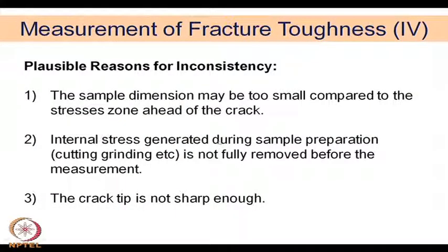ground, and annealing of these internal stresses is always difficult, because, unlike in metals and alloys, just by heating one can remove the internal stress, because it is basically a dislocation movement. Here the internal stress removal is always difficult. So, one has to take special precautions, so that during cutting and grinding additional stresses are not generated, there is no stress concentration. So, things are at their lowest energy level.